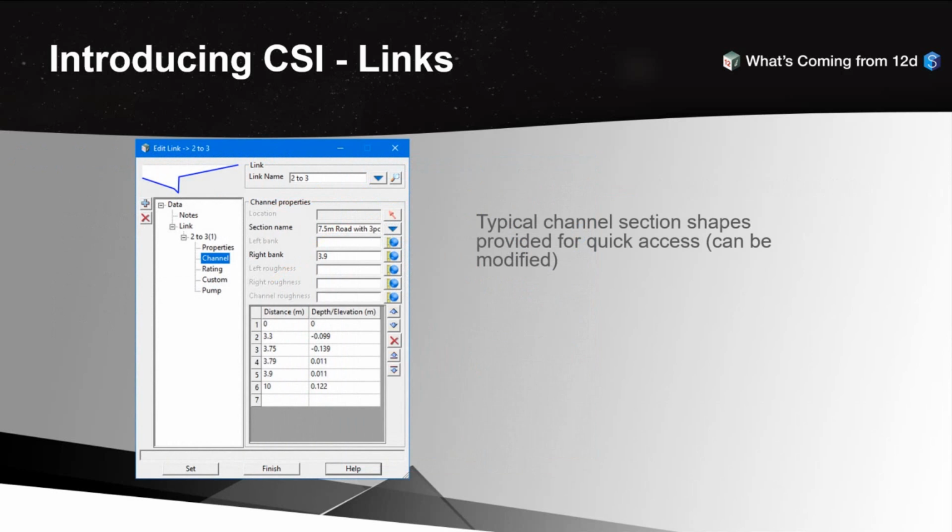Alright, so the last thing I wanted to talk about with links is this idea of having some default sections. Obviously if you're in the concept phase of your job, you don't have any design data necessarily, you may not have any survey data that you can use, but you know that you're going to have some road type that's probably going to come into play at some point. We've got these standard section types in here that you'll be able to use just for quick and easy setup, so that can save you some effort in setting values.